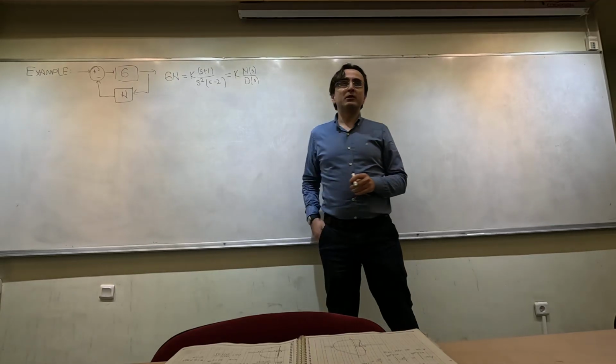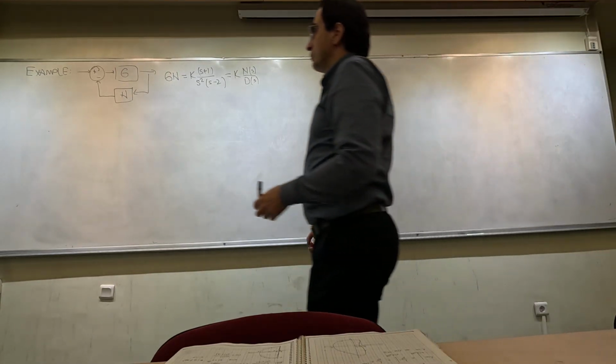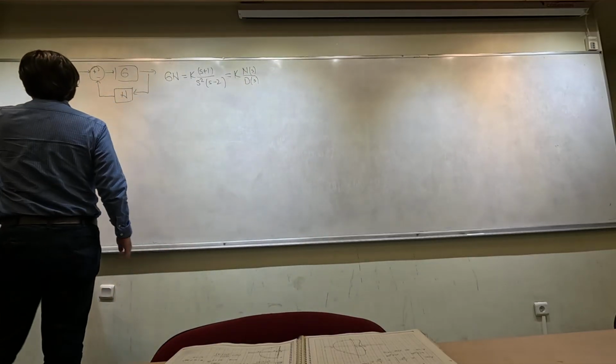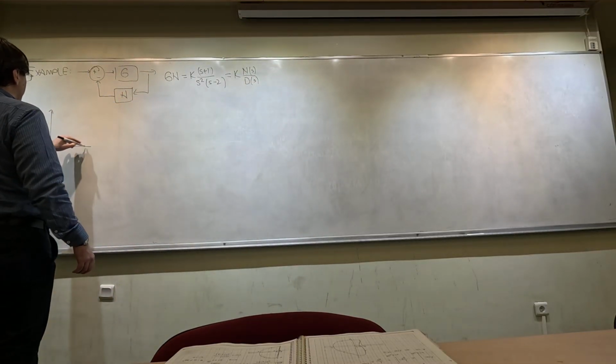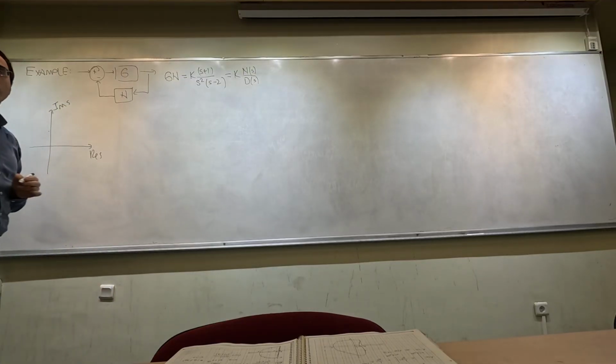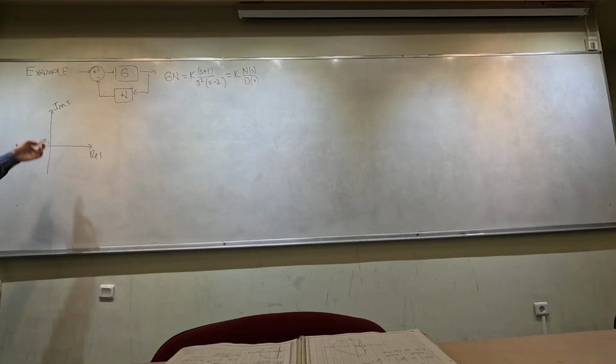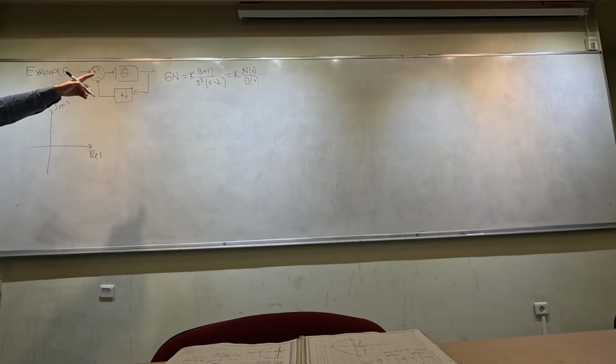Our last example in Nyquist stability criterion. And remember, we are always doing the same thing. I start with an original contour in the S-plane. This contour is called the Nyquist path, and it has clockwise direction. So I will mark the poles and zeros of the system first there.